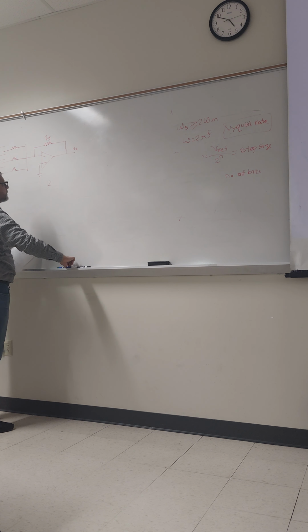So we can write I equals V ref by R times the summation for i equals 0 to n minus 1 of b by 2 to the power n minus 1 minus i. Here i is the position of the bits and n is the number of bits. This is how we can also calculate the current of the circuit as well as the voltage. The amount will be the same.